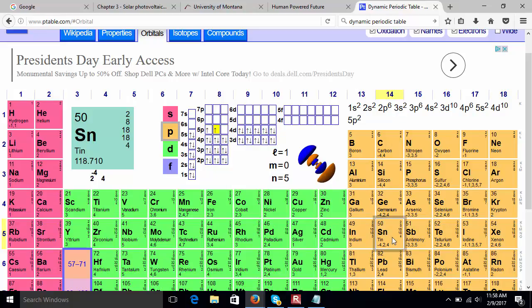One of the neatest things too, there's even a metal that's transparent. It's indium tin oxide. So if you ever see ITO, you could actually use ITO as your conductor on the surface, and you get rid of that reflection altogether.